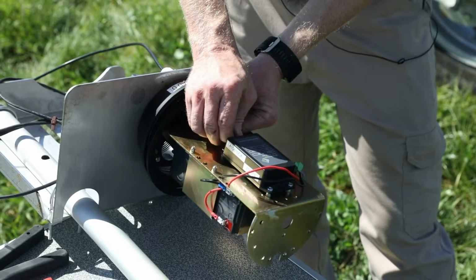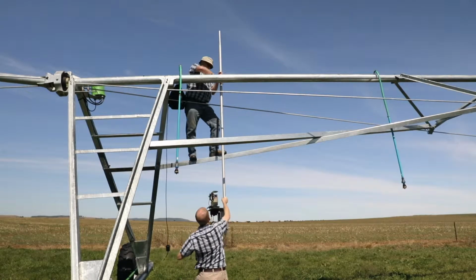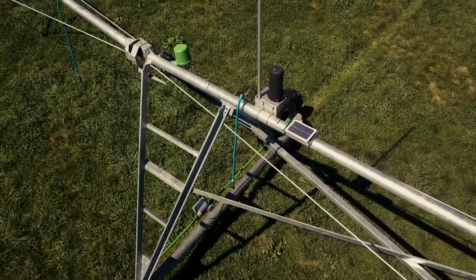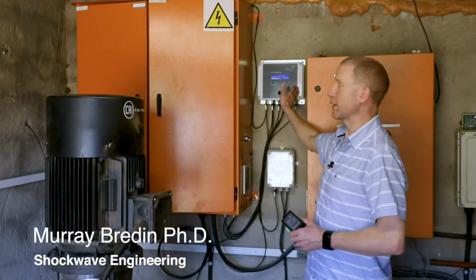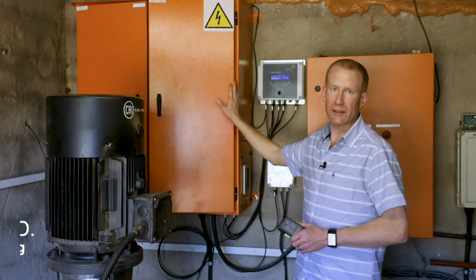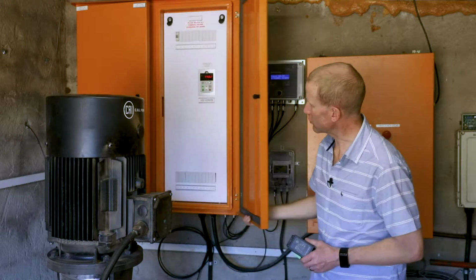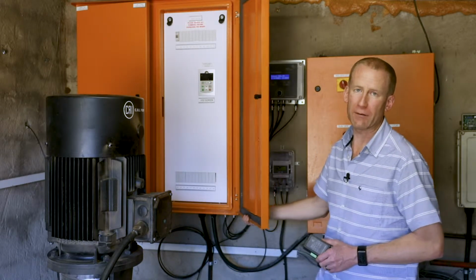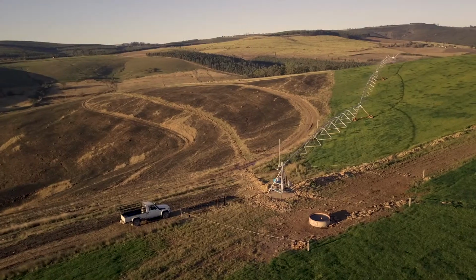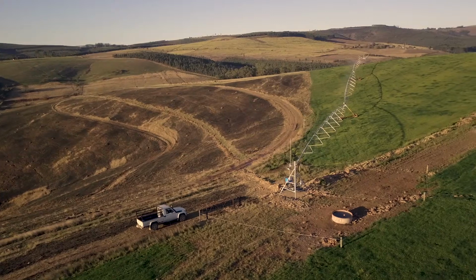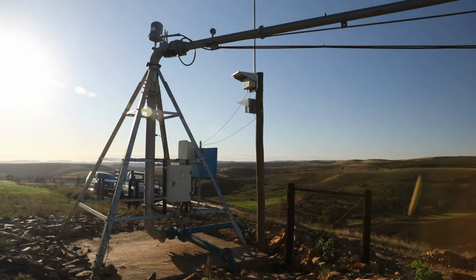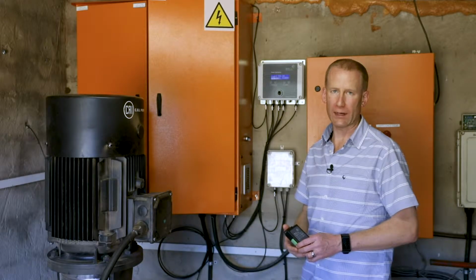A remote pressure monitoring station is installed at the center and end of each pivot. These stations transmit the pressures over a radio link to the main unit over here, which is installed in the pump house. This main unit sends a speed signal to a variable speed drive, which is installed here. The variable speed drive then speeds up or slows down the pump to get different pressures at the center and end of the pivot. The main unit receives the center and end pressures over a radio link and compares those pressures to their required set points.